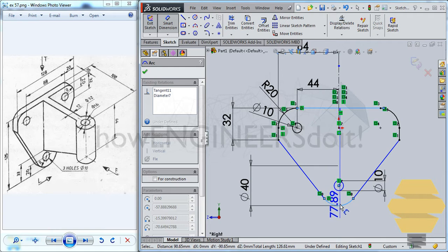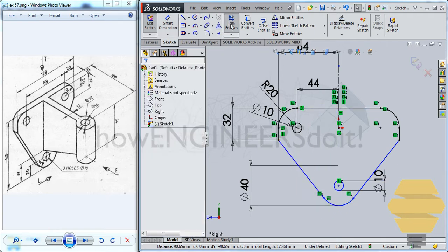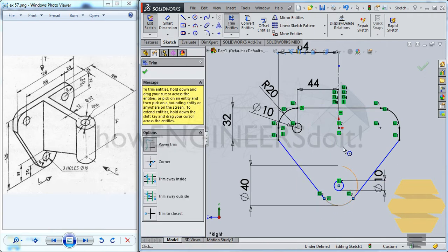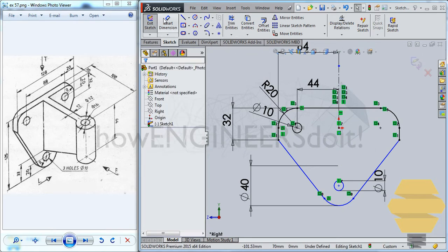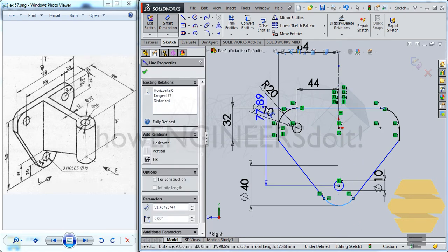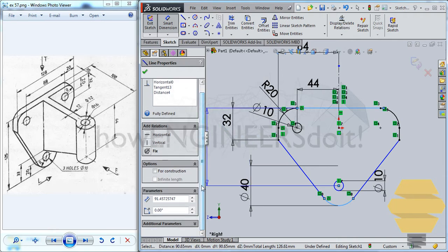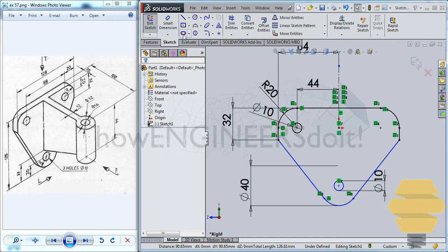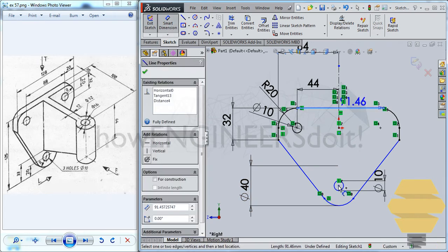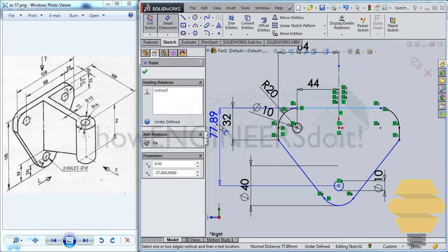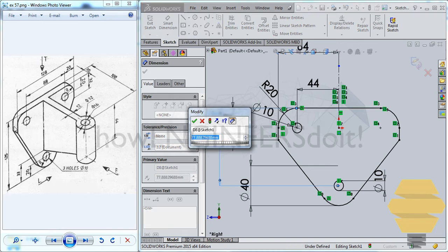That's not what we need. What we'll do is we'll go for a constraint here. Go for a smart dimension, the circle. Alright. What we'll see here is that the radius of this outer circle is 20. So we'll just do the dimension from here to this center, and you can see that the overall is 125.